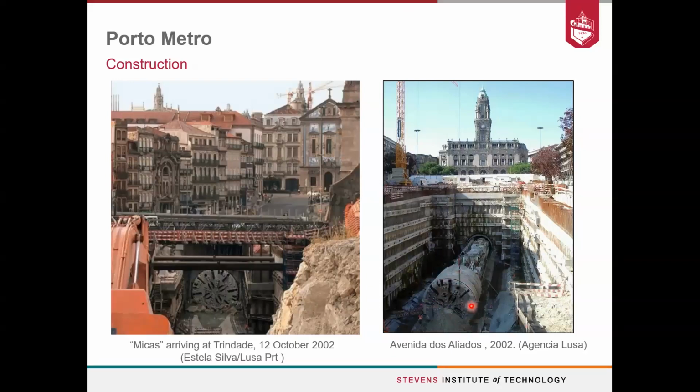That's the shield. This is about 8 meters, 20-something feet. It's about 10 meters, 30 feet. And then behind you have a train of almost 200 meters that supports all of the operations that go inside the TBM, and the operator is inside the shield, controlling and adjusting the operational parameters.